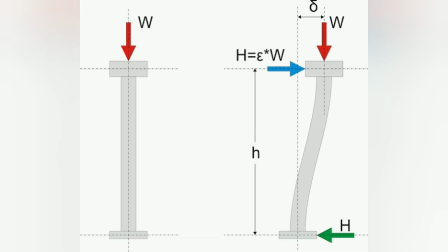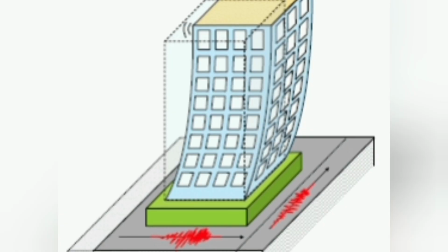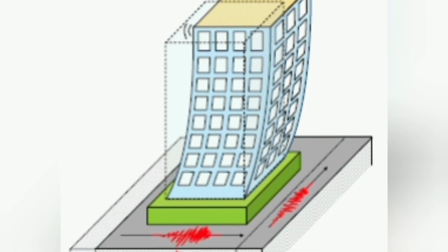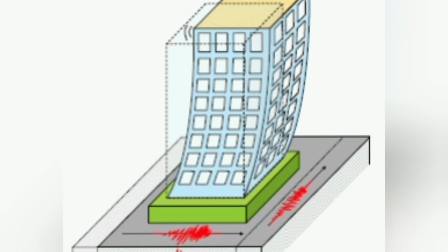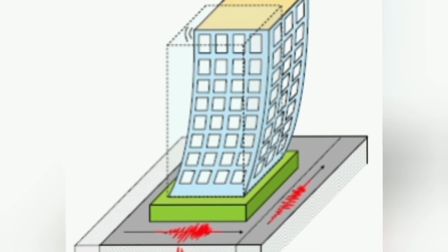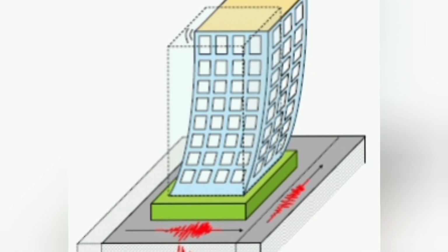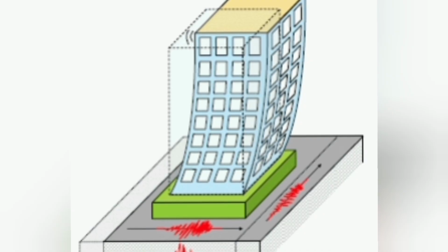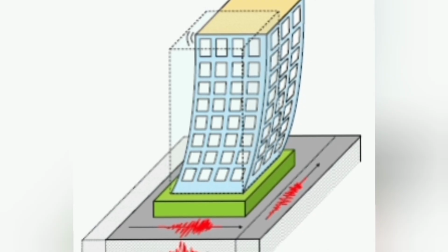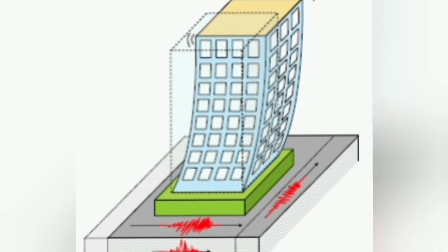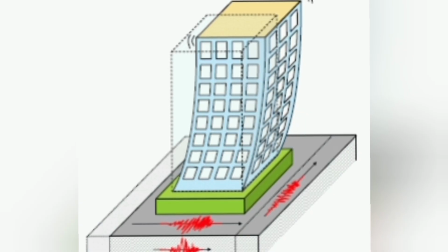The key principle here is ductility. A seismic force wants to twist, shake, and rack the building. Brittle materials like unreinforced masonry will simply crack and collapse. Therefore, seismic design focuses on creating a ductile, flexible structural system that can absorb and dissipate this energy through yielding in specially designed elements, like the beam-column connections in a moment frame or the links in a braced frame.